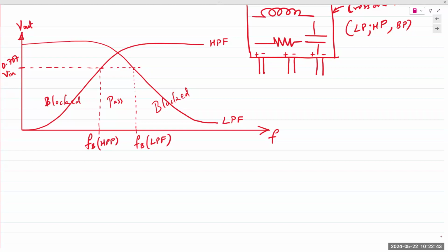So coming back to our topic, which is the resonance circuit. Electrical resonance is a phenomenon that occurs when you have an inductor and a capacitor in the same circuit. And because both of them are energy storage devices, a phenomenon known as electrical resonance occurs. And what happens at those frequencies is that at resonance, voltages and currents that are larger than the source may appear in that circuit.